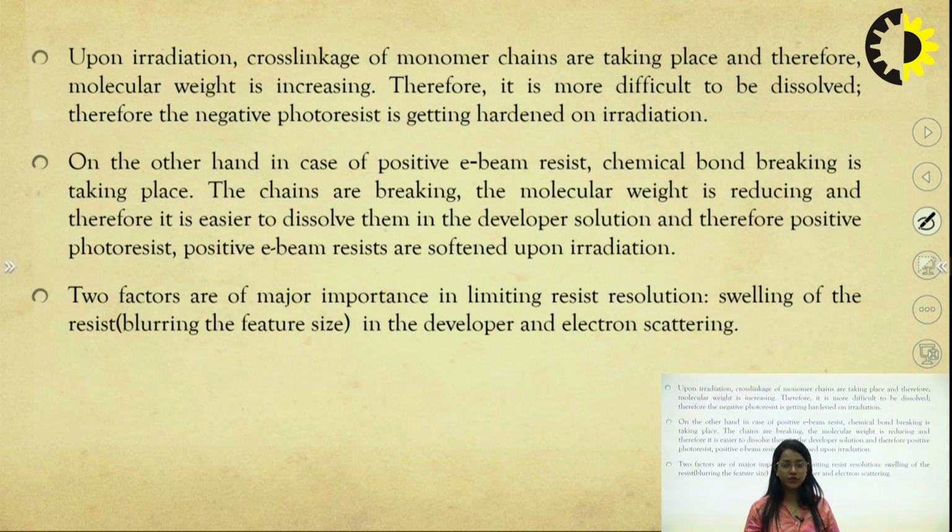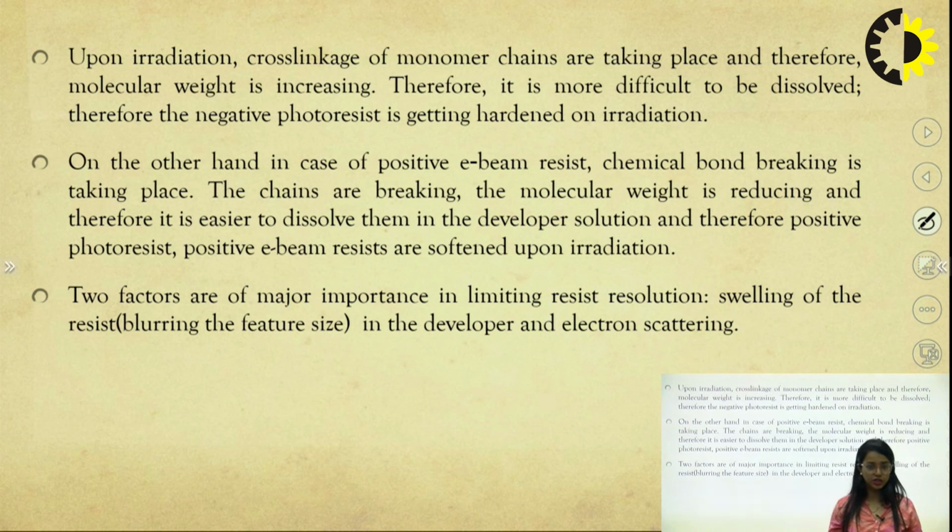So we can wash and remove the excess silicon dioxide by a process of washing and then etching. After etching, we get a clean cavity. In that cavity, with the process of ion implantation or diffusion, we add the dopants, and my next lecture will be on ion implantation, where we will be adding the dopants at particular sites. After we have added the dopants, we can strip out the extra photoresist. So that was all from my side on electron beam lithography.